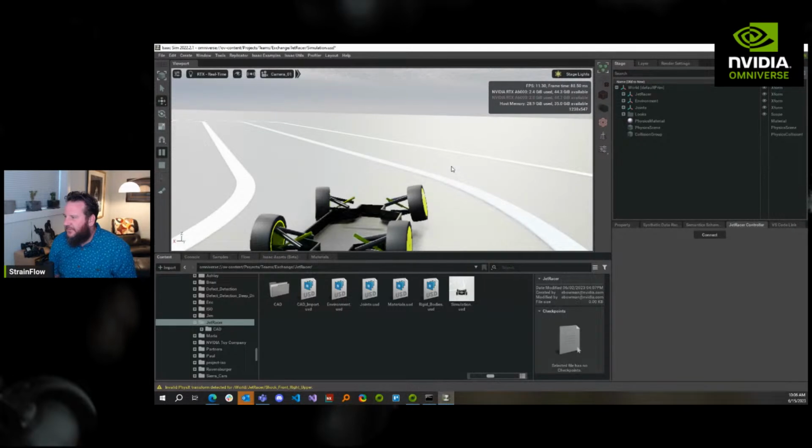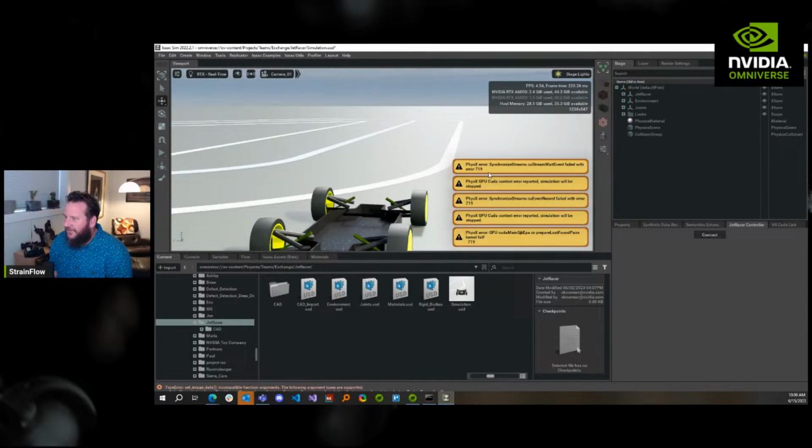Oh, there we go. Maybe we just crashed. It'll reset to the original position to stop the simulation. It's trying to recover. But in my experience, every time it crashes right now, something's up with my masses or my joints. I have a whole bunch of articulations in this, which may be more than usual. Each suspension setup, each corner, has 2 articulations, so I have 8 articulations plus 2 or 3 in the steering. It's a lot going on here. Let's give it a minute to die in peace.